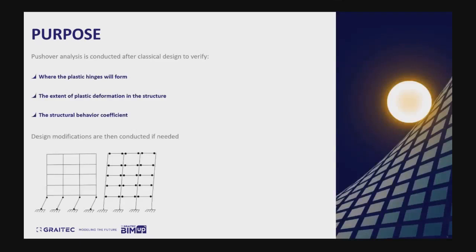So what is the purpose of the pushover analysis? The purpose of the pushover analysis is to see where plastic hinges will form inside of the structure, how far plastic deformation will be exhibited in these hinges, and check if the degree of plasticization occurring inside of the structure respects the limit states defined by seismic codes for this importance of the structure, for the proper use of this structure. And then if we need to do some structural adjustments, in this case we can do it.